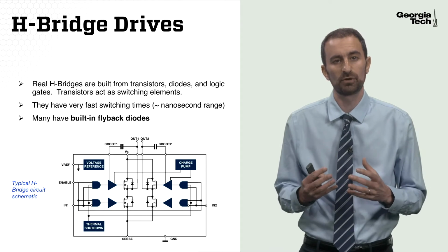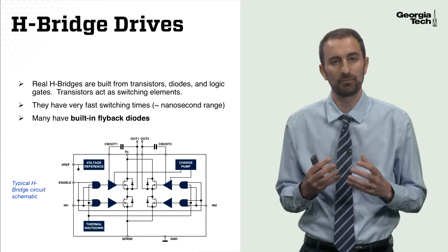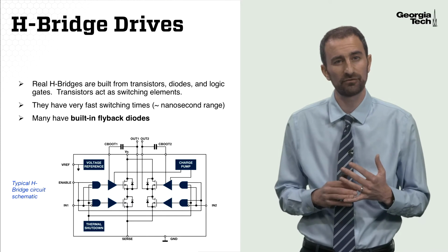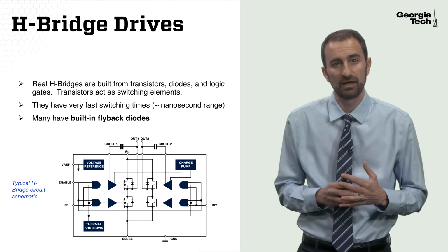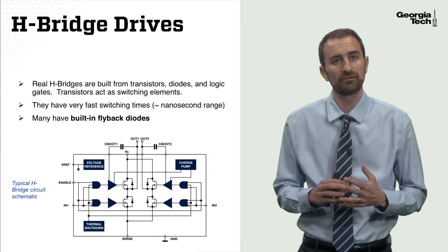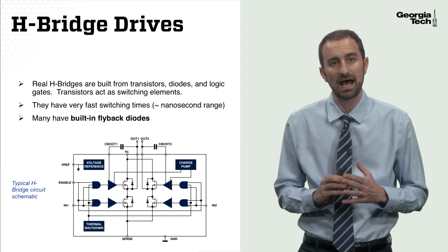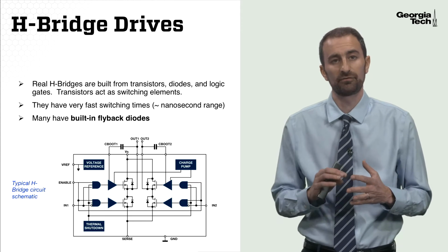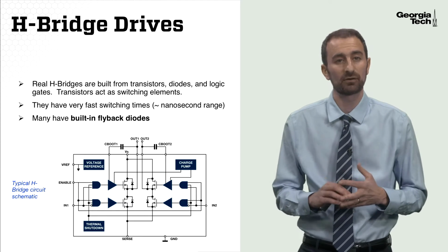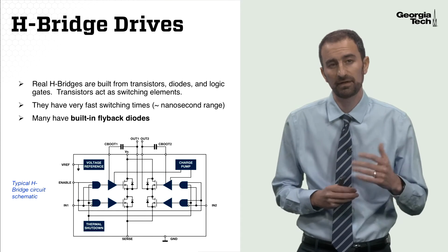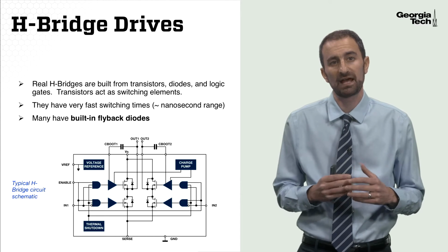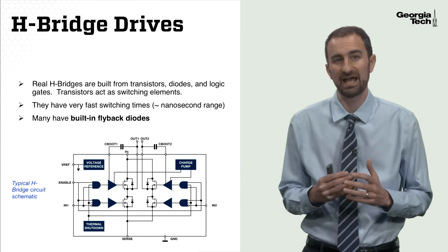Now, real H-bridge circuits are not made from mechanical switches. They're built from transistors, diodes, and other components like logic gates. The transistors act as the switching elements, so these are solid-state switches, not mechanical switches. The thing about transistors is that they have very fast switching times in the nanosecond range.